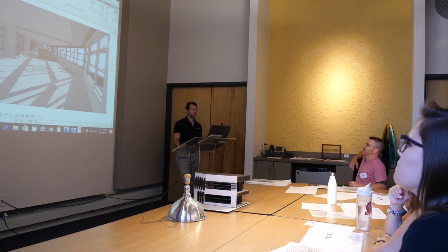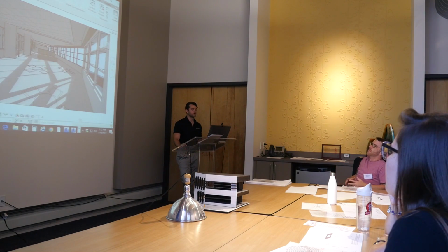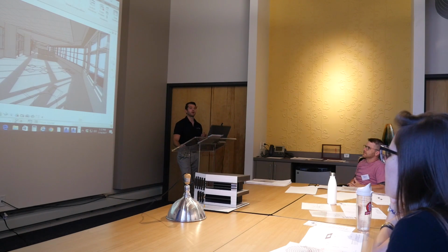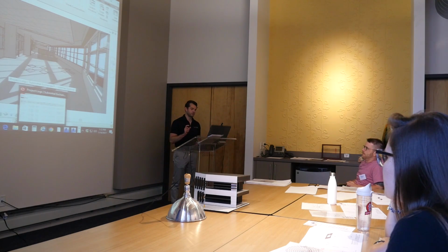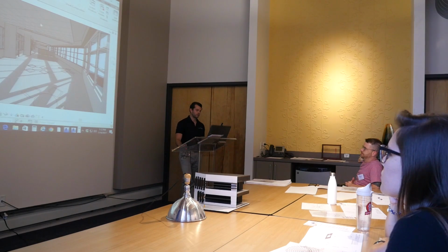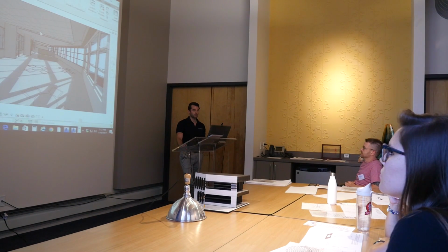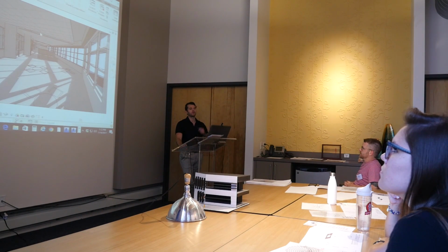And you can get real technical. We don't do this on every project, but we certainly could, where you can actually find the foot candles of how much light is hitting each space. Because you need obviously a certain number of foot candles on your desk floor. So we really can tweak the louvers and the openings to provide indirect light. So that's not only warming your building in the winter and cooling it in the summer, but it's also reducing the amount of lights you need to have running.